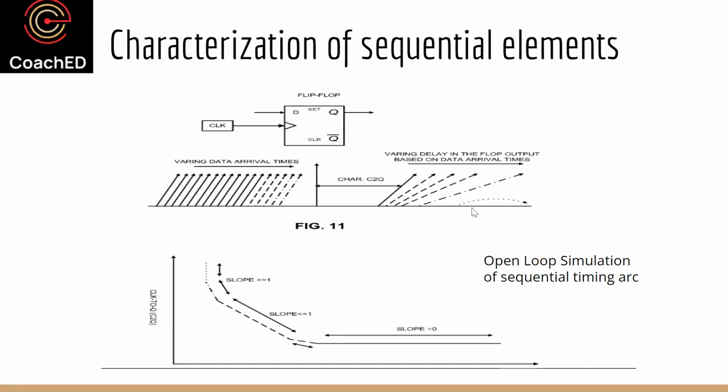So that means now you try to find the middle point. You come to the middle layer, you come to the middle and you run the simulation again. Is it passing? Is it failing? Is it misbehaving? And you repeat, and you keep doing this. If it's a passing point, you mark that as a boundary and you go to the right. If it's a failing point, you go to the left, to the middle, and you keep repeating it.